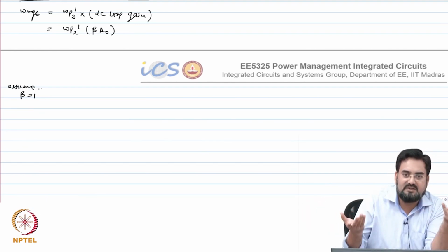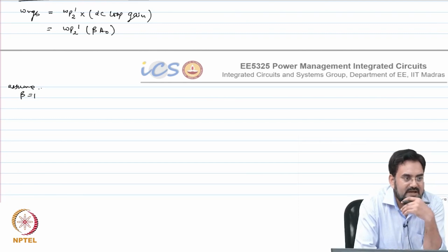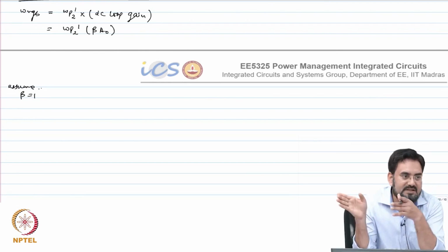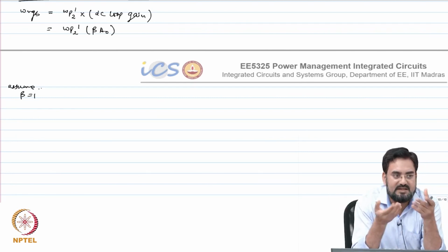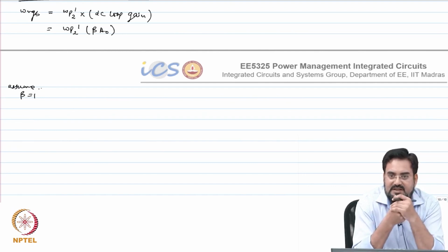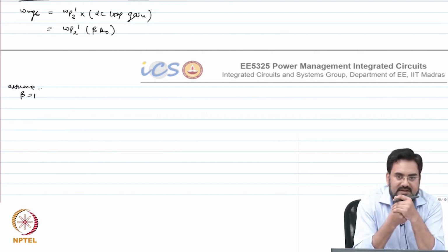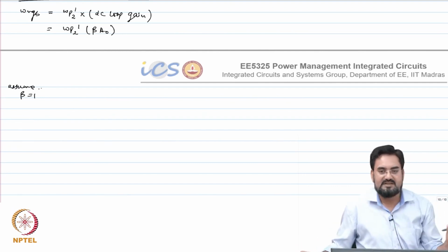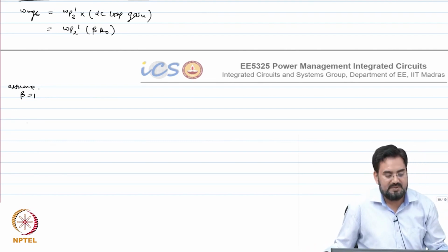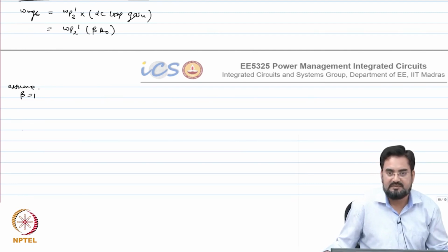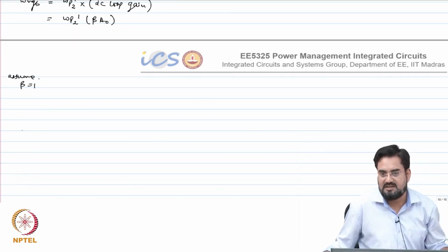So at half frequency, obviously it will give you better phase margin, because now the second pole is further away from your UGB. If you let's say approximated 1.7 times, now it will be 3.4 times away. So that's why we always compensate for beta equal to 1, so that it's compensated for all values of beta as long as beta remains less than 1.